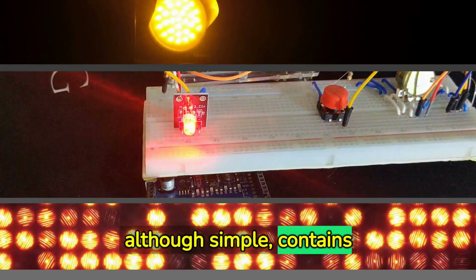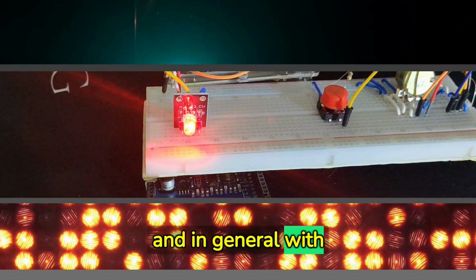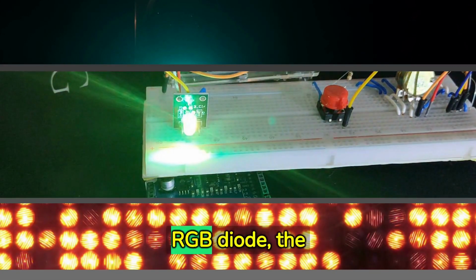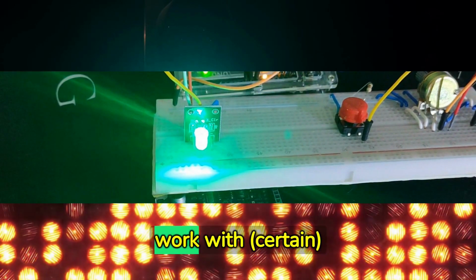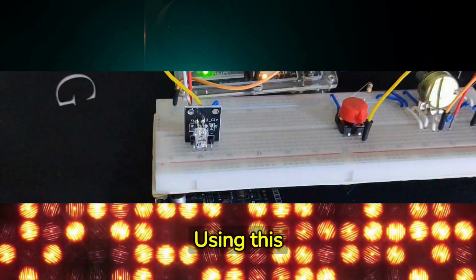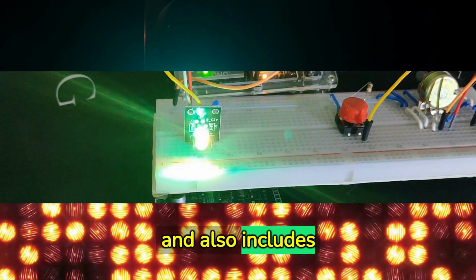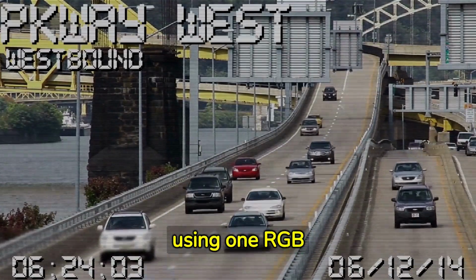This project, although simple, contains several elements essential for working with Arduino and in general with microcontrollers. In addition to working with the RGB diode, the project involves using the analog write function to work with certain digital pins. Using this function implies the use of PWM signals and also includes usage of user functions. The project represents a simulation of traffic lights using one RGB diode.